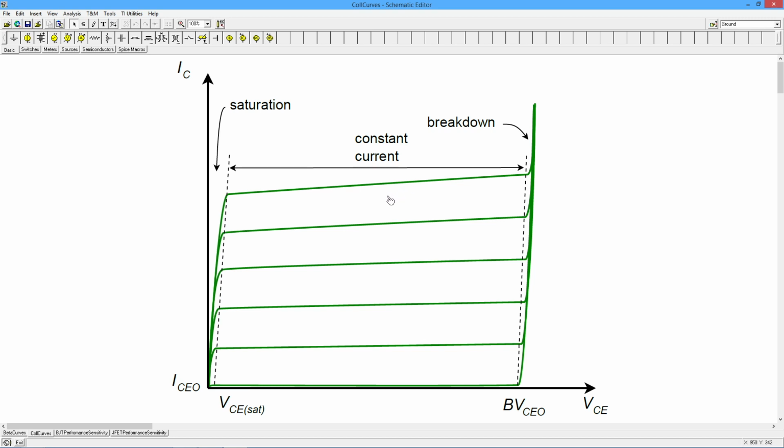Some other things that expanding that depletion region does is it changes the associated capacitance. The collector-to-base capacitance will decrease as we turn up that voltage, as that reverse bias gets larger and larger. You could think of that as two plates. The collector and the base are like plates of a capacitor, and the depletion region is analogous to the dielectric. So you crank up that reverse bias, it's like separating the plates farther apart, and capacitance goes down. So we tend not to think about that.